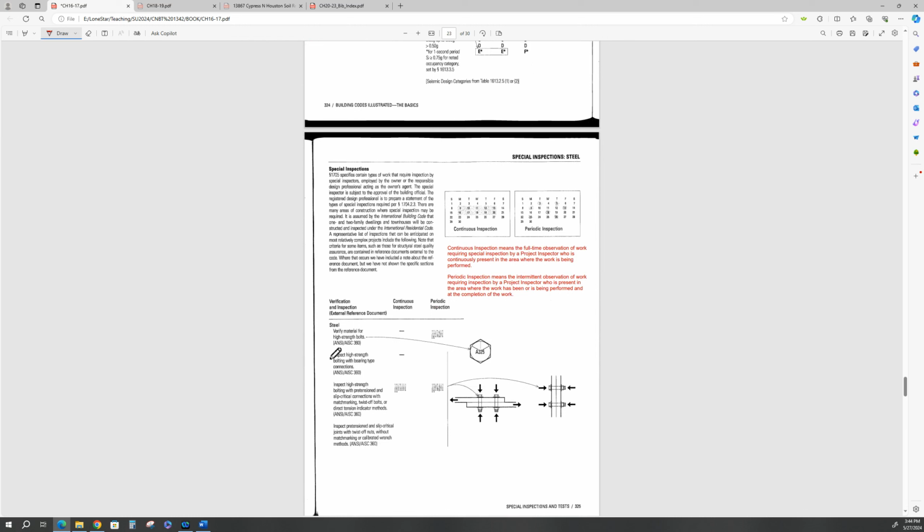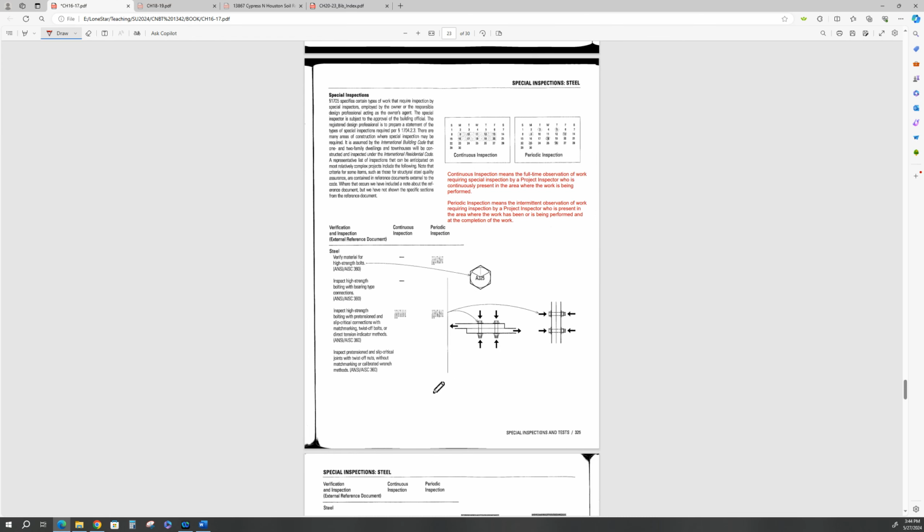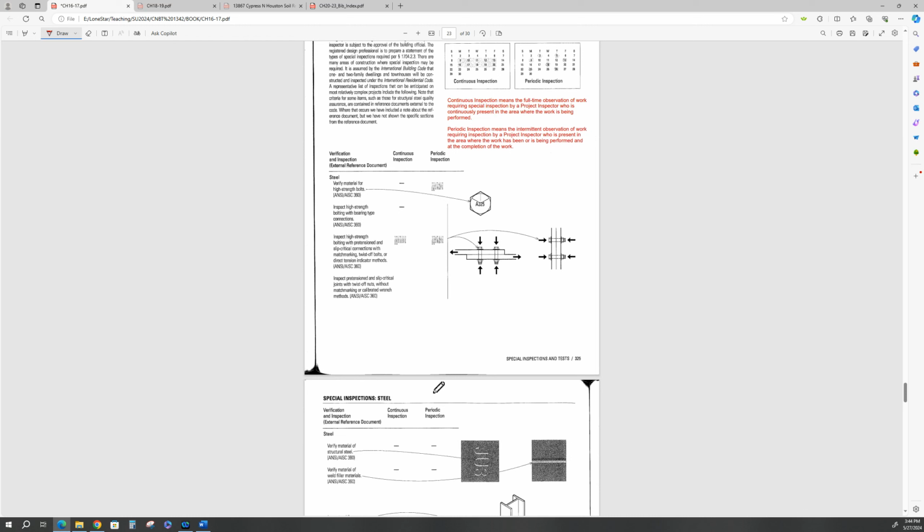Your specifications under ANSI, AISC 360 may require special bolts. Now, structural steel bolts is a minimum of A325. And my structural steel inspectors and I would go out and look at the bolts, and we would check the torque on the bolts, the torque specifications of these things. We get mill certs for the steel that they're using, welding inspection reports if they're doing welding, etc., etc., etc. Okay. All right.